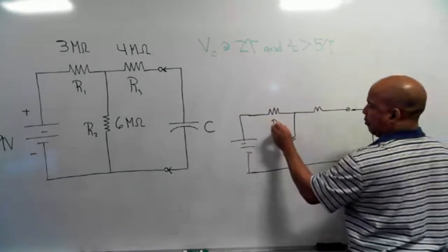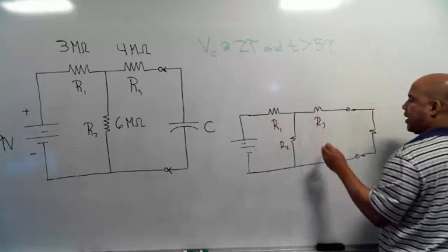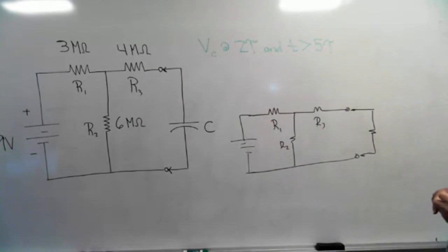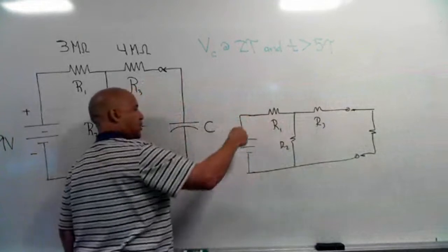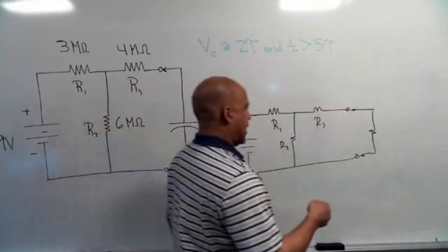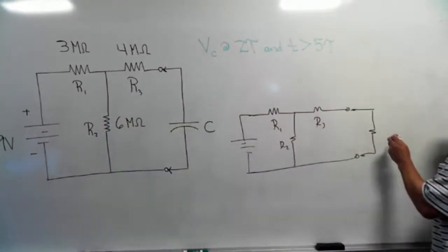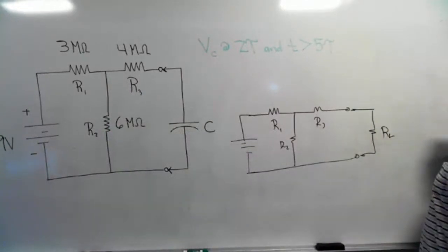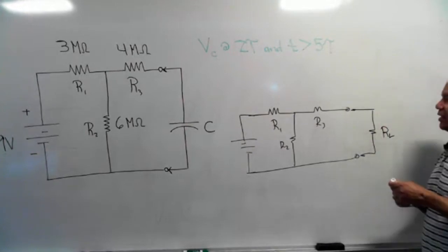I tell you that this is R1, R2, R3. If I ask for the total resistance in the circuit, remember there's two of them. There's a resistance looking this way, which is the resistance that the voltage source sees, and then there's the resistance looking this way, which, whatever resistor you name as the load, is the resistance the load sees. And the way you do that is by Thevenizing the circuit.